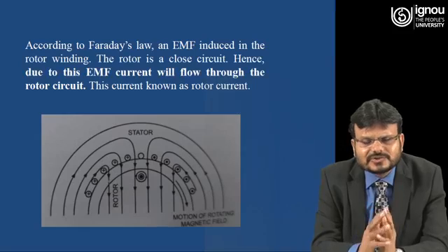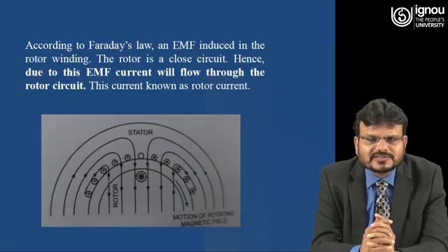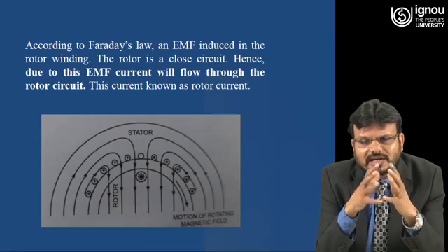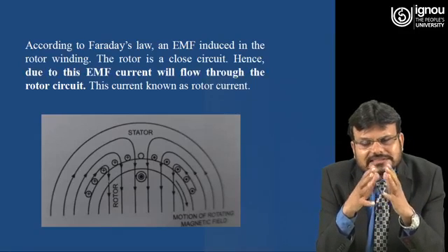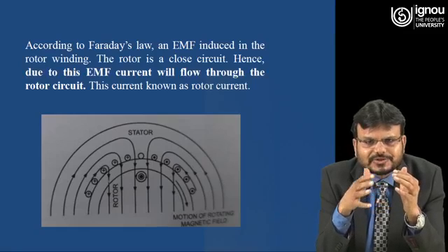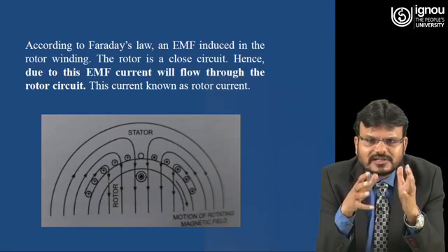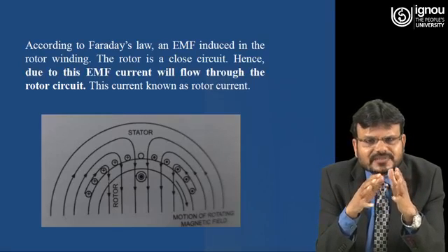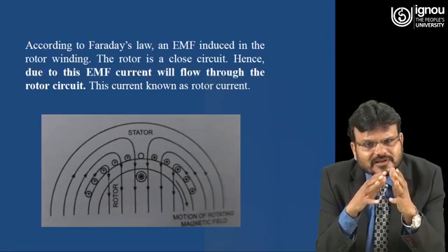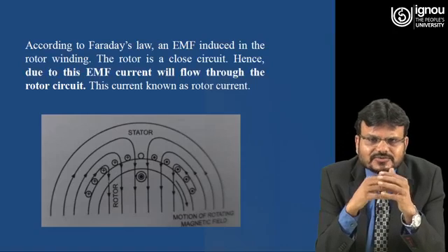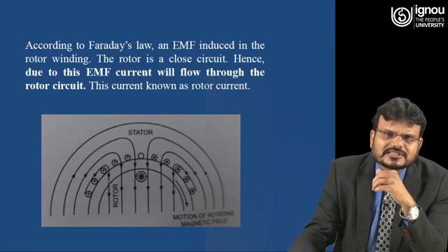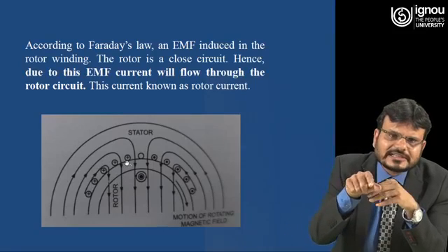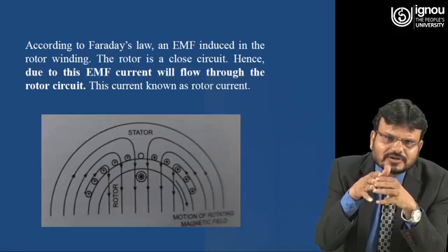So in the case of a three-phase induction motor, what is the beauty of it? You are giving a three-phase AC supply to the induction motor, and the beauty of this three-phase supply is that the field is rotating in nature. That means it is changing in nature. If this field is changing and some conductor is placed in it, there will be a relative change in flux linkage, and EMF will be induced. Here you can see in the diagram, this conductor with a plus sign shows that the direction of the current is into the paper, or you can say the slide.